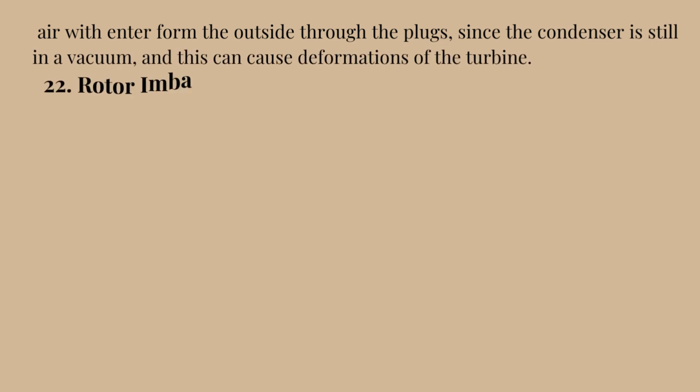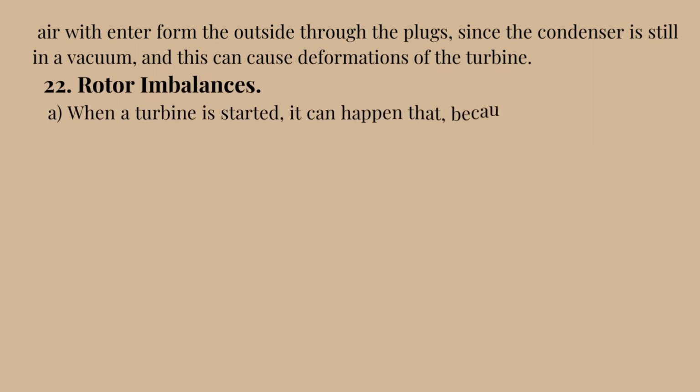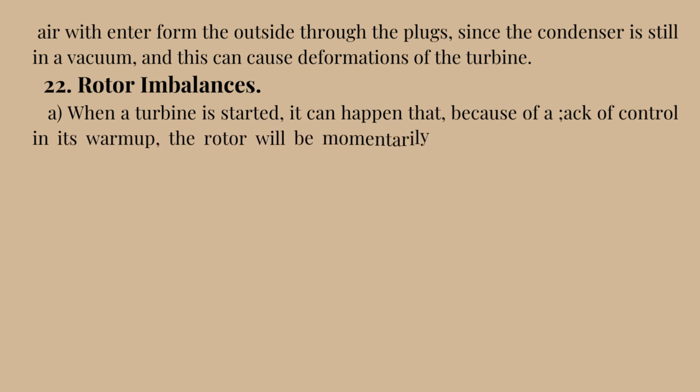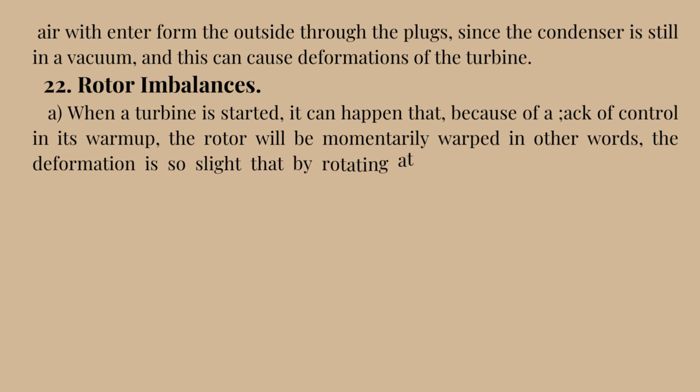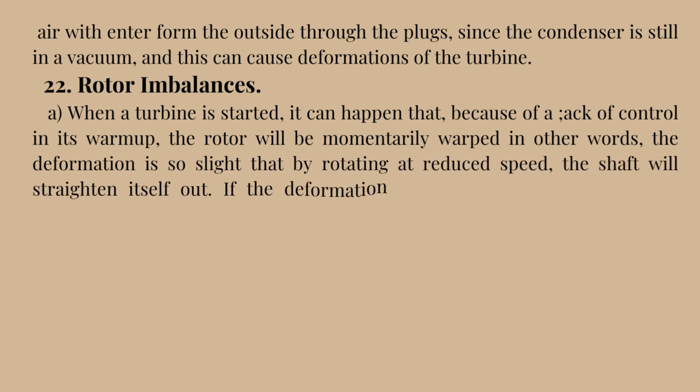22. Rotor imbalances. A. When a turbine is started, it can happen that, because of lack of control in its warm-up, the rotor will be momentarily warped. In other words, the deformation is so slight that by rotating at reduced speed, the shaft will straighten itself out.